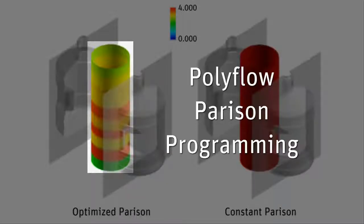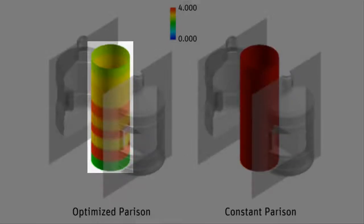The parison programming feature provides an answer to the following question. What should the initial thickness of the parison be to meet a targeted final thickness? In theory, this question may be asked for each point on the part, but for practical purposes, it's typical to target only key points on the final part, and to divide the parison into sections, or stripes, that initially have a constant thickness throughout the cross-section.